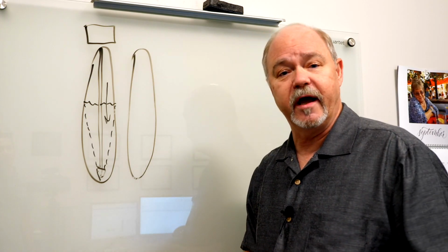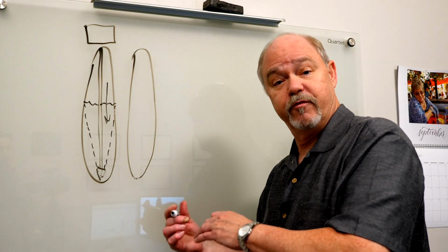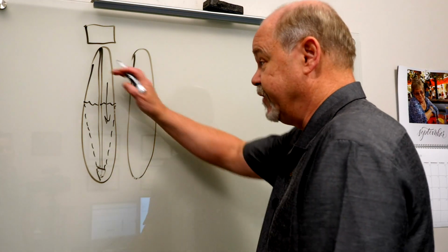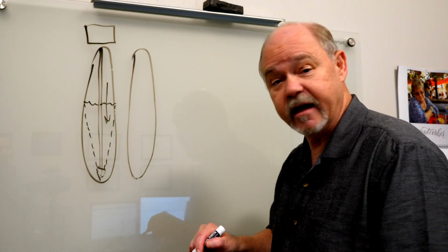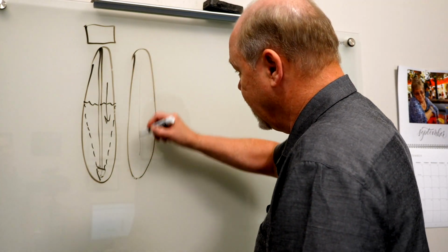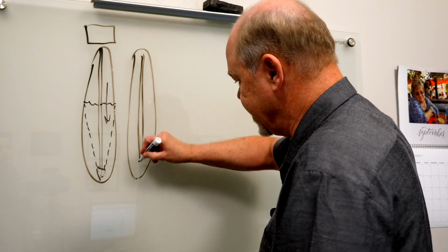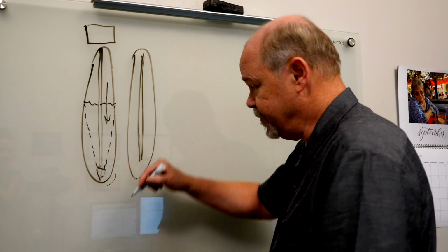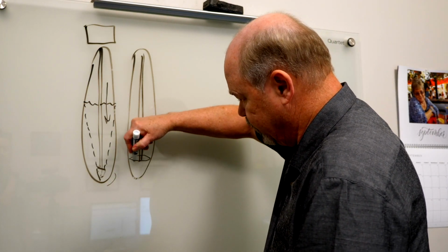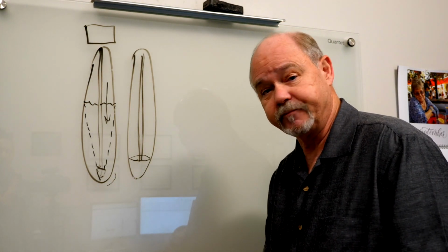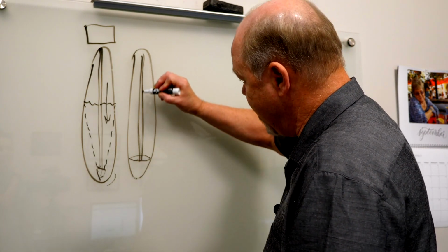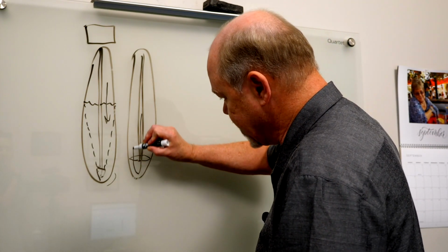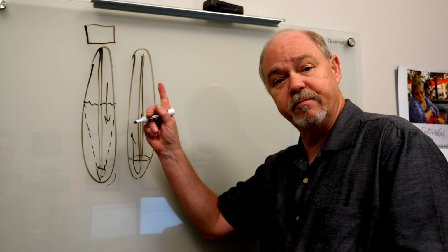So here's why we like the upflow with the vortex tank system. We've got the same size tank. We have a distributor tube that comes down the center, but instead of going to this distributor basket on the bottom, there is what's called a vortex plate down on the bottom. And water flows down the riser tube and comes up through that plate into the media.